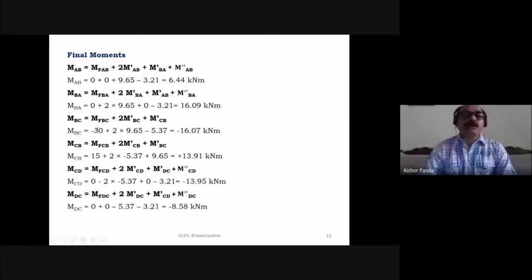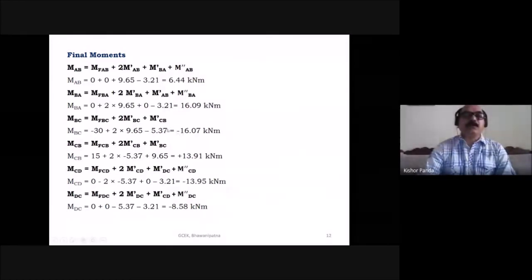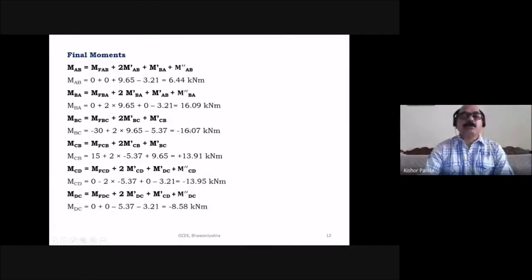MBC is MFBC plus twice M dash BC plus M dash CB. So here you know MFBC is minus 30, and twice M dash BC is 2 into 9.65, plus M dash CB, which is minus 5.37. So here no need to take the translation moment. So this is equal to minus 16.07 kilonewton meter.